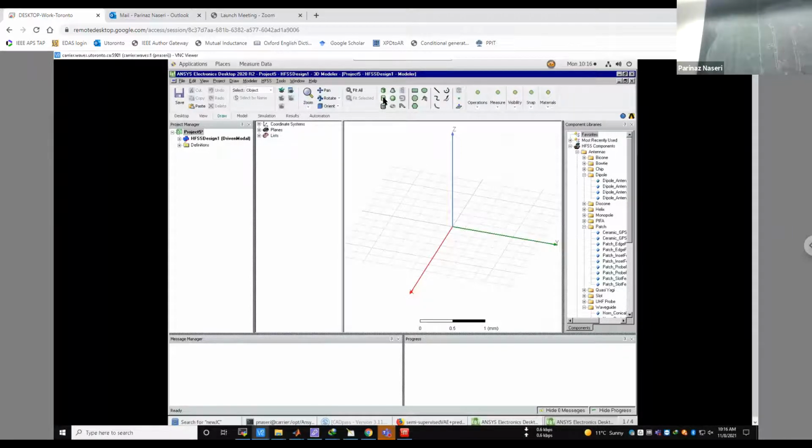So this is the problem we have. Let's say for an easier case, and this is what you should do actually. When you're designing an antenna in HFSS, always try to go with something that would take less time to simulate. We'll talk about it in a planar structure as well. But as I said, it takes less time to simulate this, so you can easily simulate it quickly.